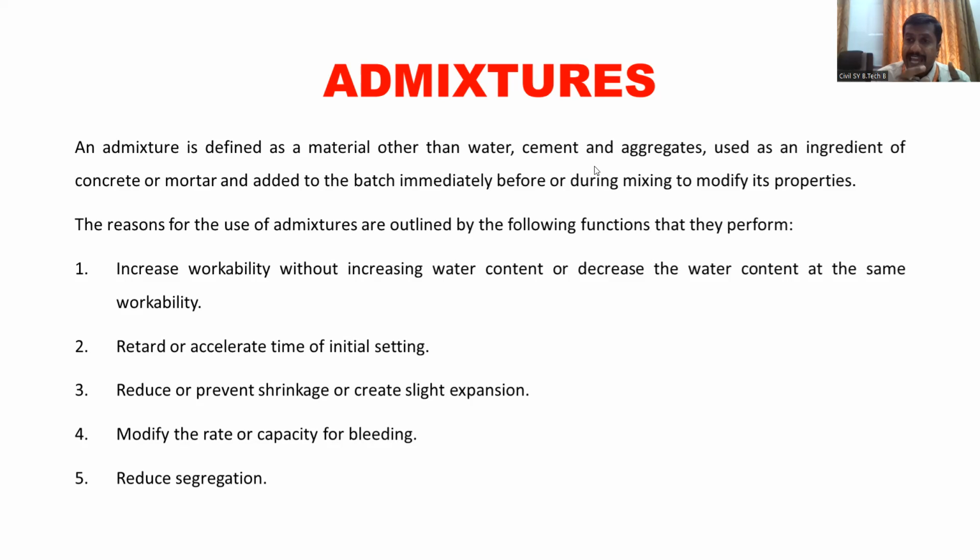So these admixtures will play a vital role in accelerating the rate of heat of hydration as well as in slowing down, or retarding, the rate of heat of hydration. Then next, their function is to reduce or prevent shrinkage and to create a slight expansion, just to avoid the shrinkage. Shrinkage is nothing but a change in the volume of the concrete with respect to its original volume.